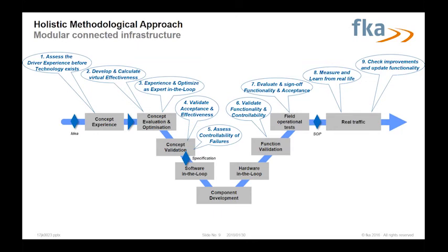For example, if we talk about platooning, we have to solve the question in the beginning. Is it good to have a gap of 5 meters? Is it good to have a gap of 10 meters? Is it good to have a gap of 20 meters? Should we include lateral control? Should we just use longitudinal control? These are quite important steps we can identify quite early in this development concept, and I will show you later how we can do it.